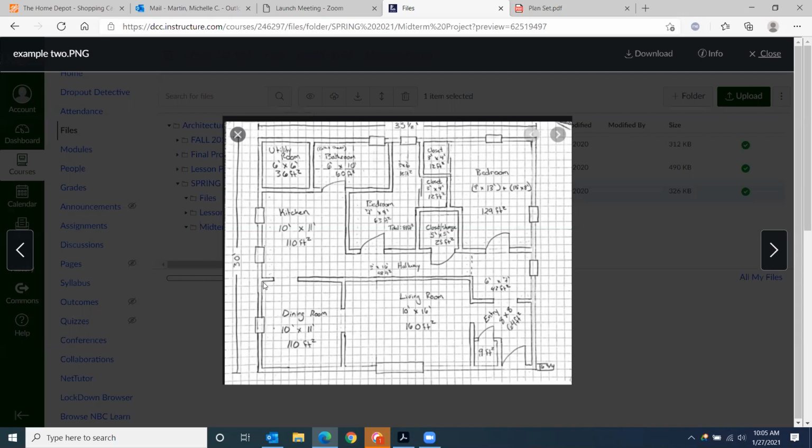And then you're going to want the measurement from this wall to the interior of this opening, the size of the opening, and then this measurement here to this measurement here. Once again, another 3 measurements, and then 3 here. Measurement from this wall to this opening, measure the size of the opening, and then opening to the wall.